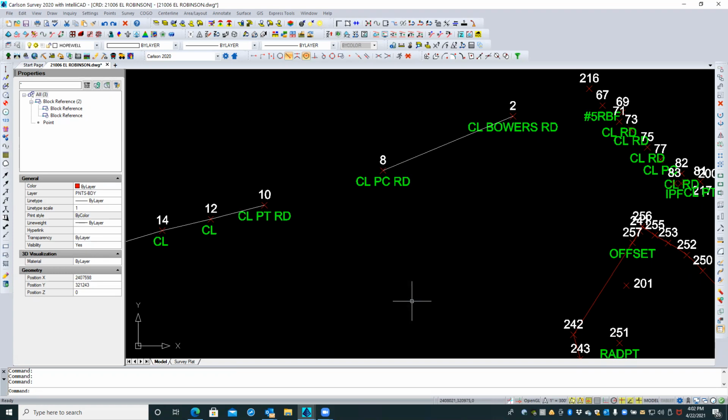So now, field to finish works in 3 possible ways. It reads this, and actually 4 possible ways. The least involved is when you just say PC, and then you shoot a point on the curve, and then you shoot the PT point and just keep going.